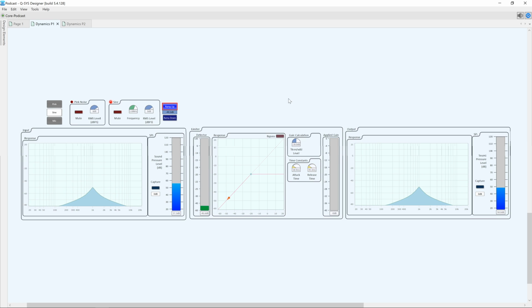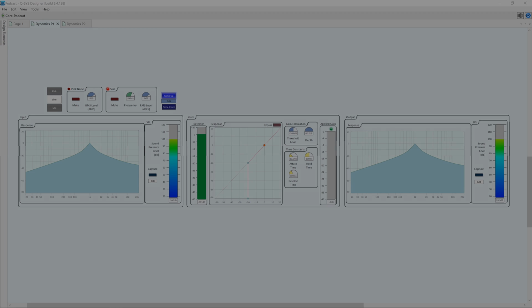So these are great for protection. You can use them for drums to help level out the signal depending on how the drummer is playing. You can also use a compressor. A compressor is very similar to a limiter. A limiter is a compressor with an infinity to 1 compression ratio. That is the only difference.